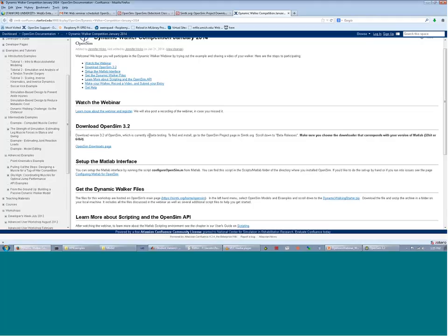So I think to answer the question, not completely. You can use the GUI, that's free and open source. You can also edit model files in XML, so you can use the XML browser in the GUI to find the markup for the component that you want to add and add it to the .osim file that way.